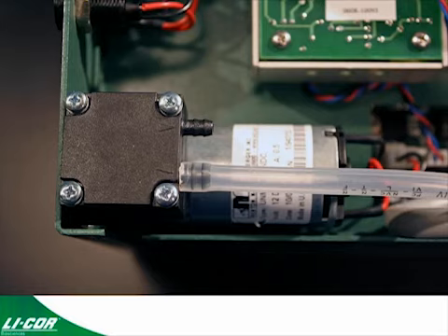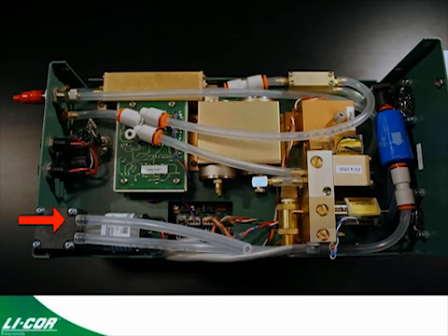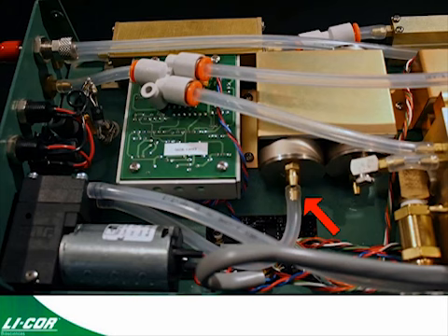Connect the other end of the tube to the pump. You want to connect tube 1 to the inlet side of the pump. The inlet side and the outlet side of the pump are marked by an arrow that indicates the direction of the flow path. Then connect tube 2 to the outlet of the pump. Reinstall the pump and then connect tube 2 to the lower barb on the first buffer volume.